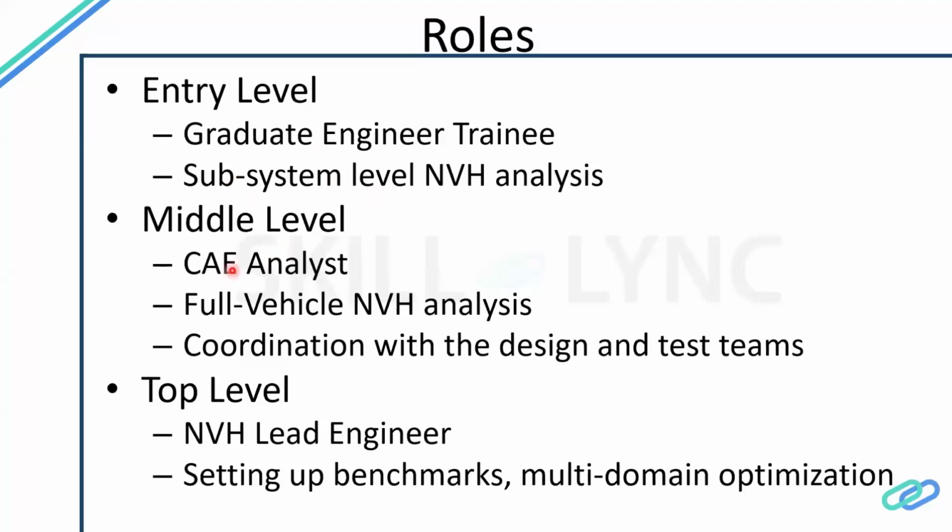Then once you become a CAE analyst, maybe after a few years of experience, you start working on full vehicle NVH analysis, where you will consider the effect of different subsystems, say how electric motor noise is affecting the passengers or the driver, and how the steering and suspension system should be optimized with respect to the vehicle structure behavior.